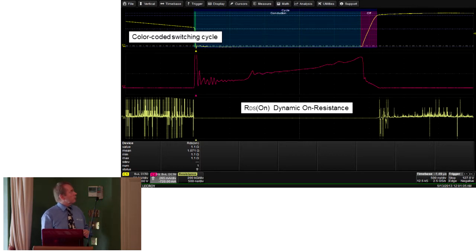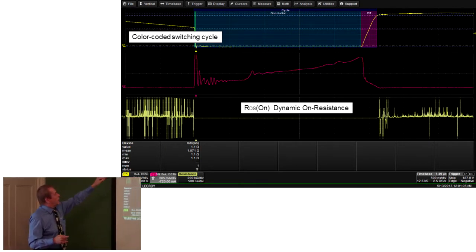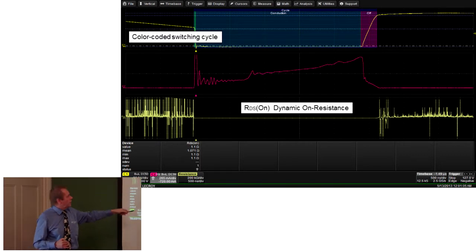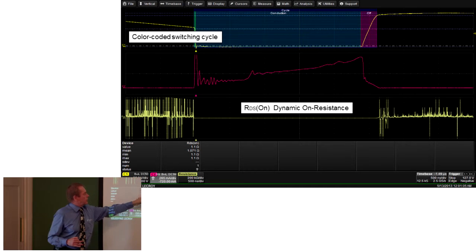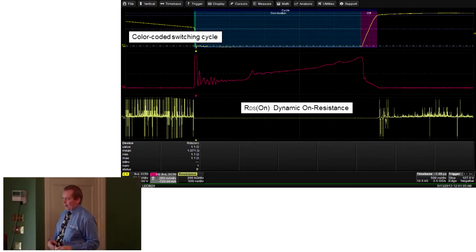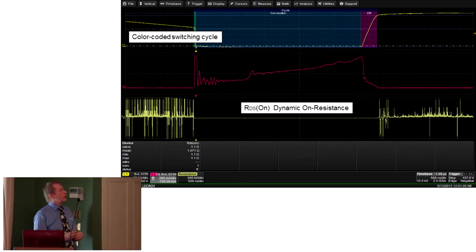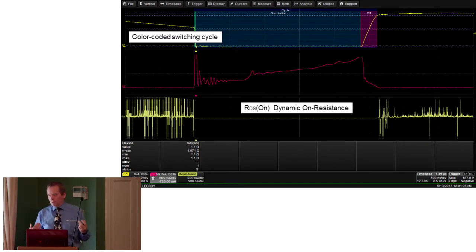This is the RDS on that I was talking about. This is interesting. So now you can clearly see that it's 50 volts per division we've got on the top here. We're doing the measurement, and what it's doing is multiplying out as the voltage gets down to the 0, and then it'll do the calculation for you and tell you exactly what that resistance is. If you try and do that with an 8-bit, and obviously we make 8-bit scopes as well as 12 bits, you'll find you can't do that with an 8-bit.